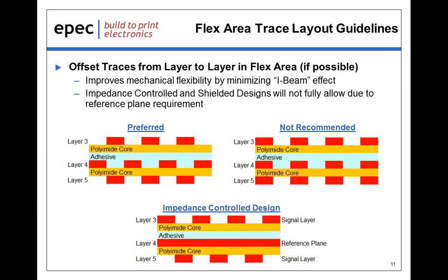This has a positive impact on the mechanical flexibility of the design by eliminating what's referred to as an I-beam effect. And again, it's a piece of cheap insurance. If it's possible, we definitely suggest that it be done. As you can see in the not recommended image there, where the traces line up from one another, it will constrict, it will stiffen the flex areas, which in turn restricts the flexibility and could, under extreme situations, create reliability issues.